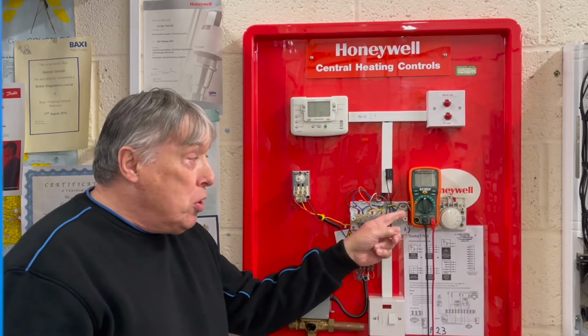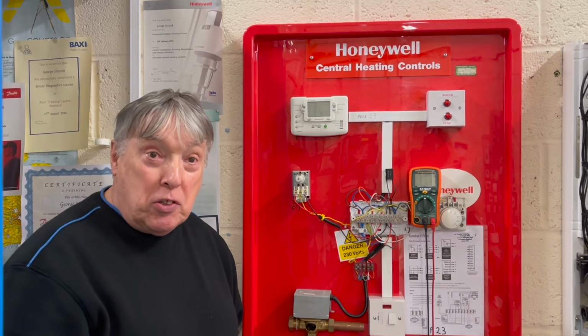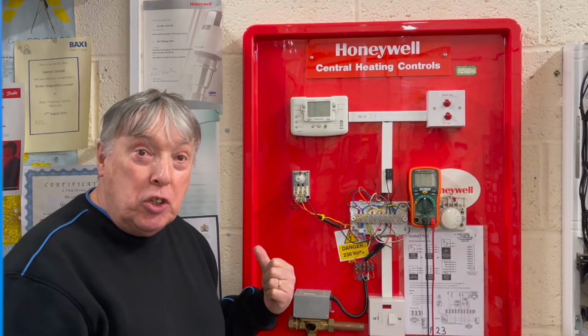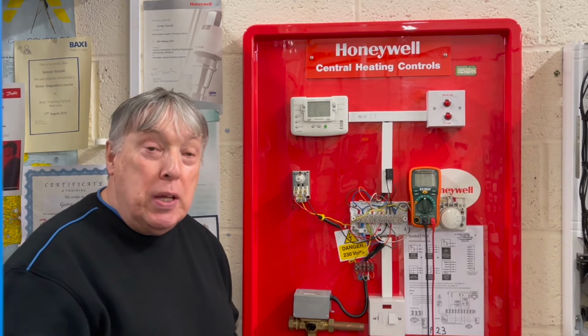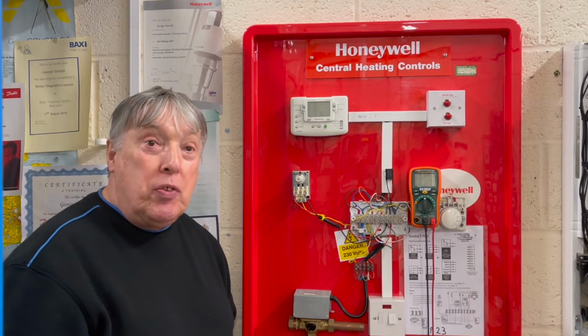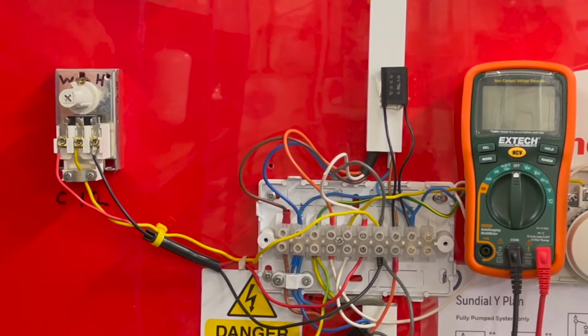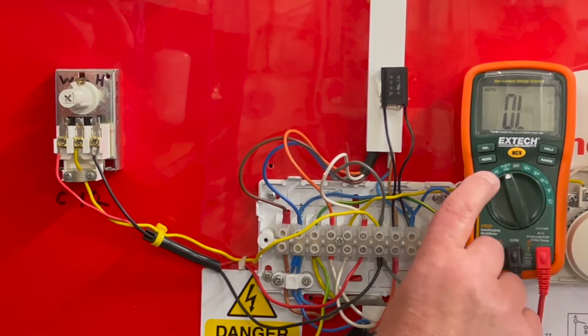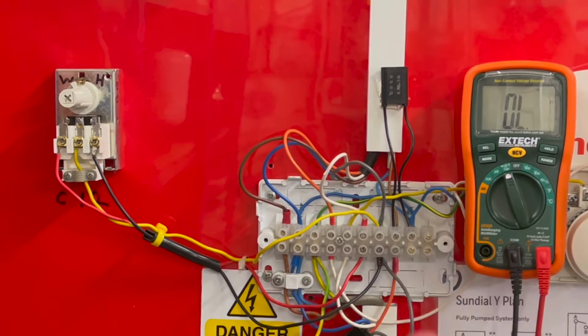We're going to put the multimeter into buzzer mode because we don't need electricity, because it's dangerous. So let's zoom in and proceed with the testing. First of all, what we need to do is put the multimeter into buzzer mode. So there we are, we'll go to ohms, press it twice, and then test. Ignore the numbers because we're in buzzer mode, so it doesn't matter.